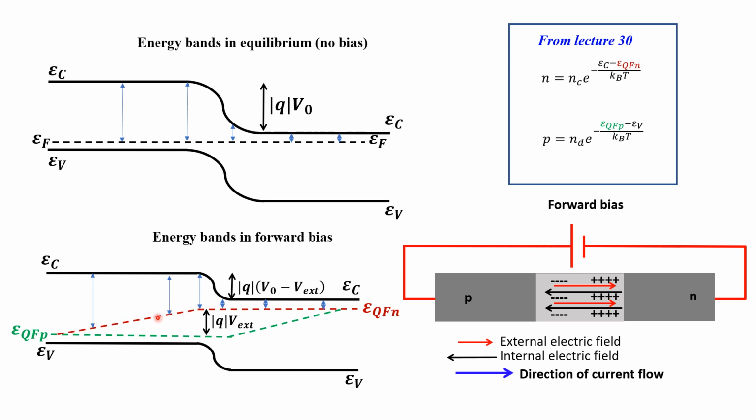I'm representing here a linear decay, but the decay is not actually linear. We're going to consider mathematical analysis in the next two lectures. What is important here is to notice that the Fermi level goes down as we move away from the depletion region, because this distance increases due to the process of recombination. So the concentration lowers due to recombination until it reaches the value of equilibrium.